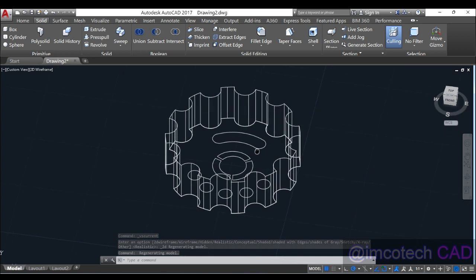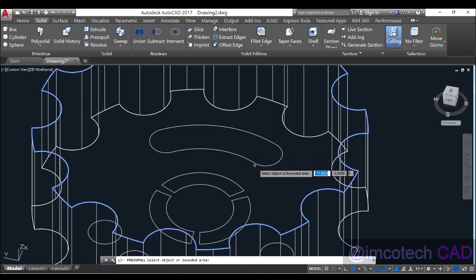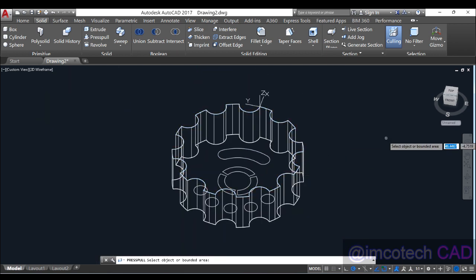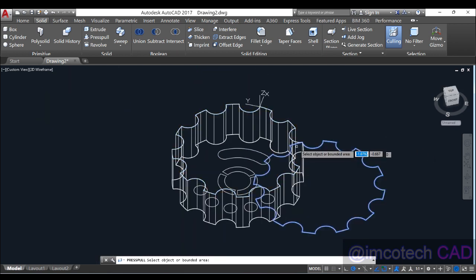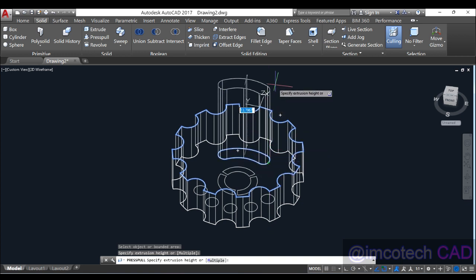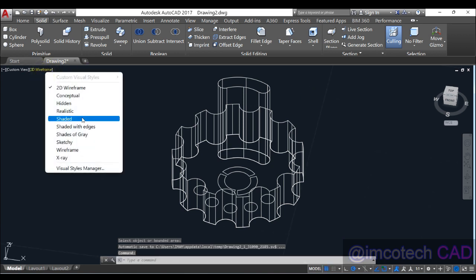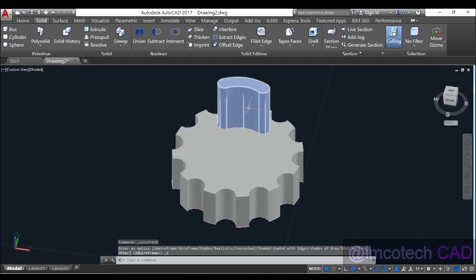Okay, how do I do that? First and foremost, I can simply press pull it. Okay, press pull. Make sure you try to select it well, so you don't select this face. If you select this face, it will increase the height. So select this and go up. I can just decide to release, right, because I want to make it as a hole, a single hole. Let's go back to shaded maybe. So can you see this?